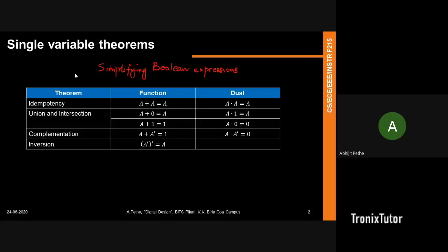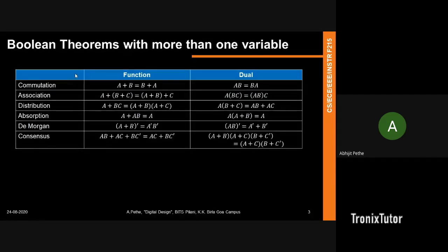So these are the simple Boolean expressions. All this you've done in Math 1, it's simple linear algebra. And then these are some of the expressions you'll use: commutative, associative. The key expressions that you need, which will be used most of all, would essentially be De Morgan, absorption, and consensus, right? The rest of them you've done in algebra, so it's not something you're seeing for the first time. Just these three are the most important things which you probably may not have done in algebra before, so this is good to keep in mind when you're dealing with Boolean functions, okay?